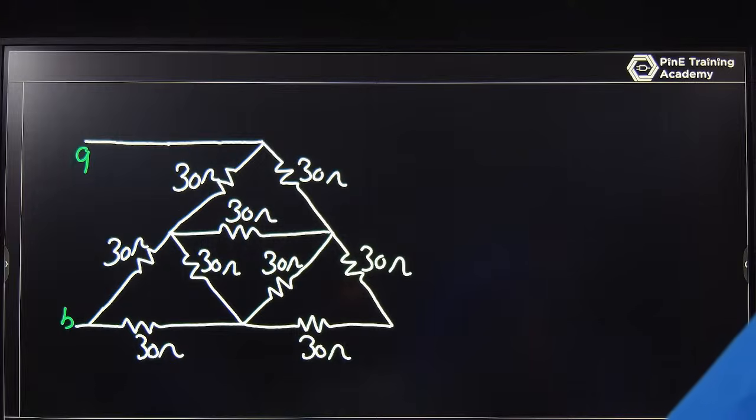As we discussed in the last class in terms of the inverter, the input impedance of the MOSFET is infinite, so there is no loading effect. Because the input impedance is infinite, the current is zero, there is no voltage drop, so the output of the previous circuit will be the same as the input of the MOSFET. So that's why it is required for you.